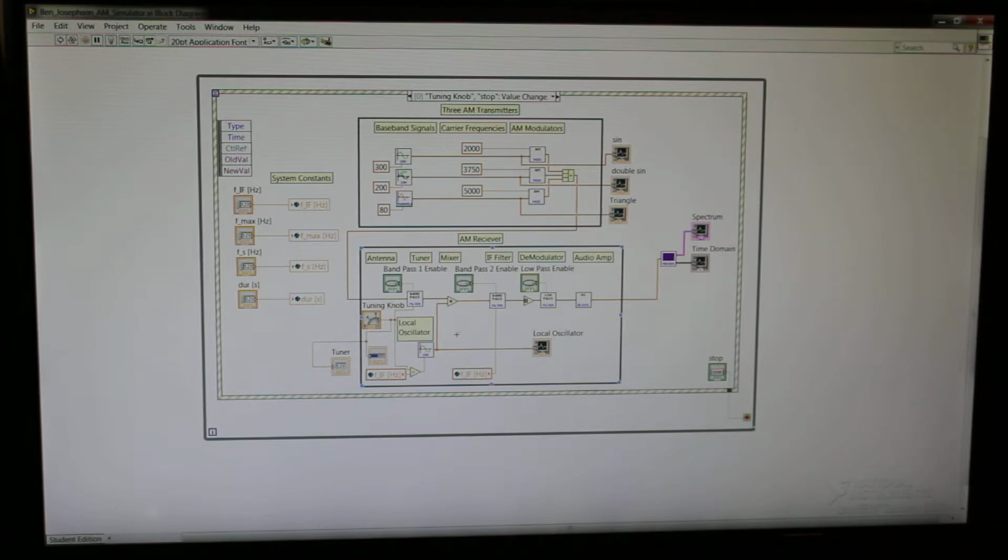We do generate some additional frequency noise in this process, so we use a second bandpass filter to attenuate the unwanted signals. We then take the positive frequency here. We go through a low pass filter which gets rid of all of the high frequency reproductions of the signal that would cause interference. And finally, in the amplification stage, we block out the average DC signal that is a result of the carrier wave in order to clean up our actual message frequency.